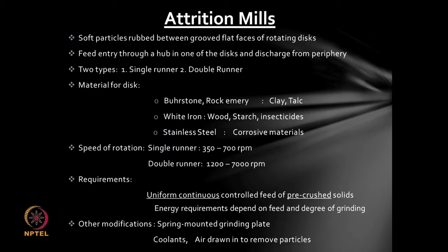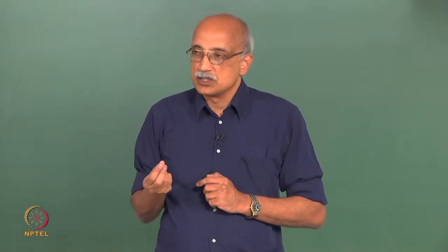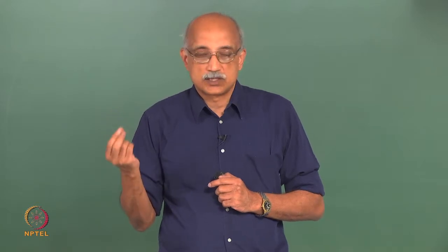In fact, the other technique that we had discussed earlier, which is size reduction using ultrasonics or acoustic fields, again works very well with ceramic particles because they combine hardness and brittleness, and that is the ideal combination for size reduction. Now you can imagine if you take a plastic particle and you try to size reduce it, it's very hard, right, because it's very soft.